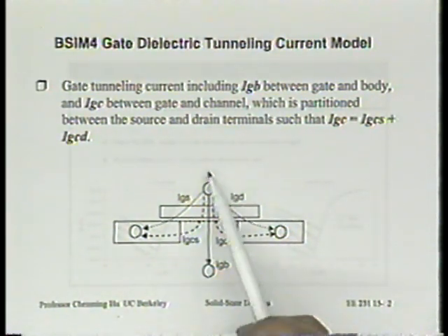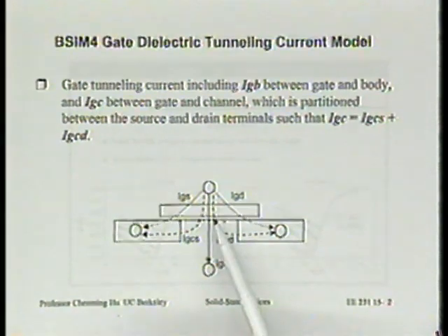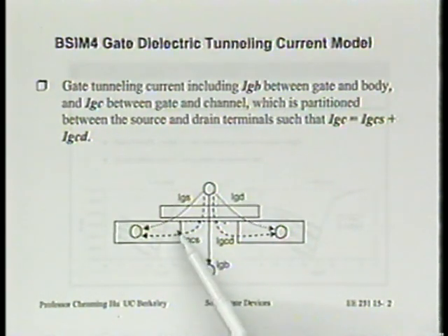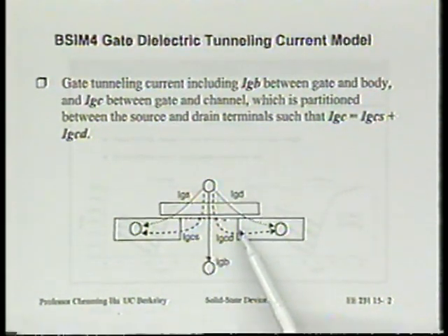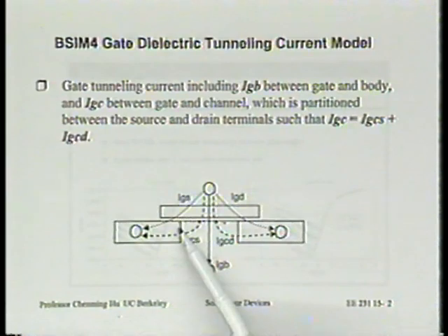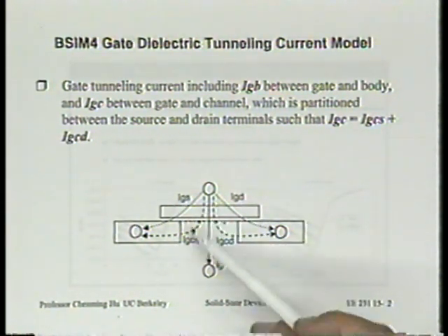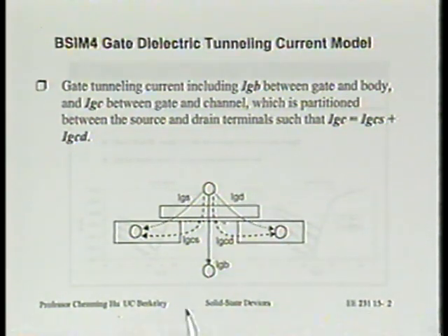Beyond the fact that there's additional current due to the gate, what about the initial current? Would that be disturbed? After all, the initial current is a very peculiar solution that happens to satisfy all the requirements of Q inversion and the field and the mobility and the velocity to get a constant current. Remember that? Now we have this additional third thing coming in from the side. Is it going to modify that?